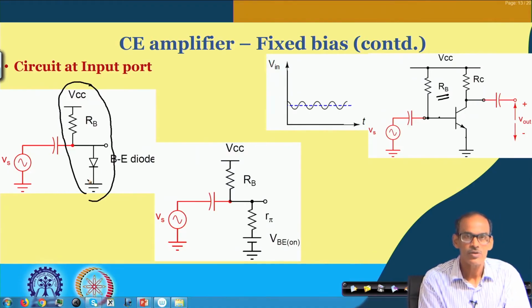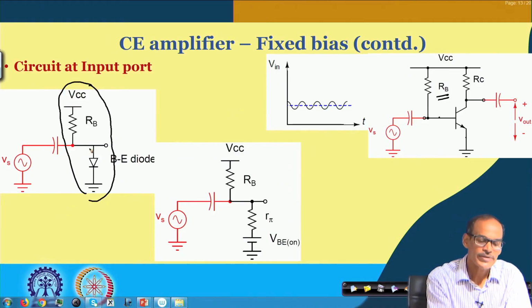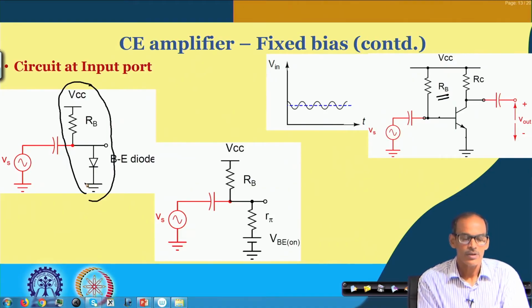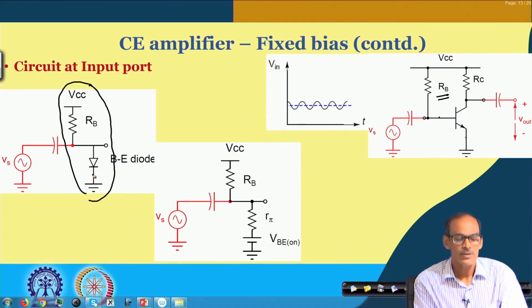Of course, this diode will be slightly different from a normal diode, namely this junction, though it is forward biased, but most of the collector currents are coming from the emitter junction. So, as a result the level of current flow here will be less. However, if I consider the current and voltage characteristic of this diode, obviously it will have the exponential relationship. So, for this analysis definitely we can consider this is similar to a normal diode.